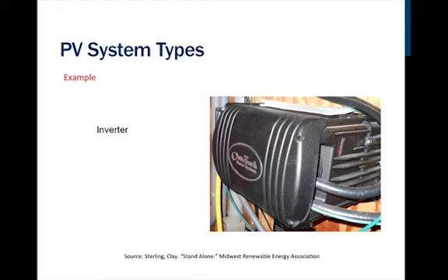From the battery pack is the inverter. Generally, not always, but generally, standalone homes are going to run at 120 volts instead of 240 volts. And everything's going to be AC power in the home. We're not going to have DC appliances or DC lighting or whatnot. Everything will be AC in general.